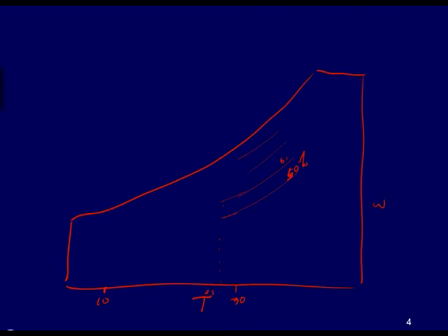Here I've sketched a psychrometric chart a little bit for you. You have temperature, and you have omega, the absolute humidity, and relative humidity lines. Here's, say, 90, 80, 70, 60. Go down to 60% relative humidity and 27 degrees. And that's our point 1, state 1 coming into the evaporator.